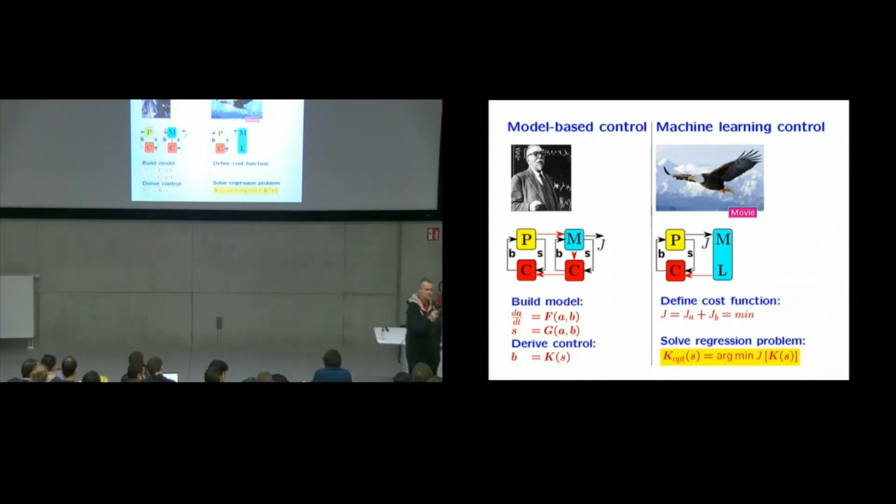For instance, one thing, you use a fluctuation as your agent, and the fluctuation changes the base flow via the Reynolds stress. And the next thing is if you do constant forcing, then you change the base flow directly. So this is the brute force killing of the instability: you can change the base flow directly, or you can use the Reynolds stress as your agent. And at the end, you typically live on a manifold, the manifold which is determined by the Reynolds equation.